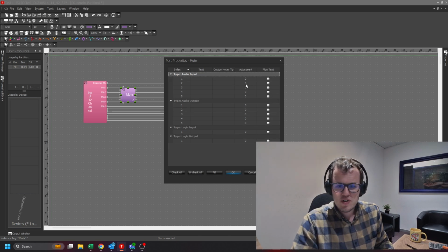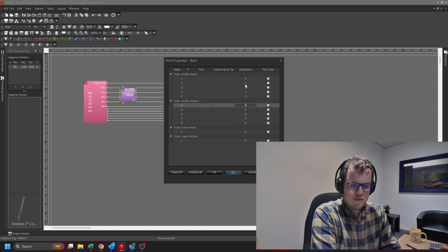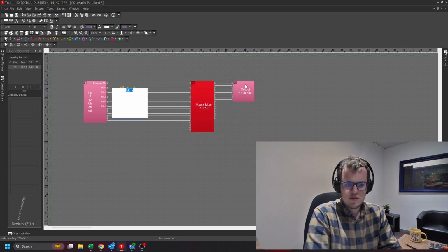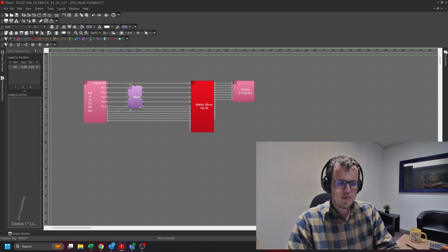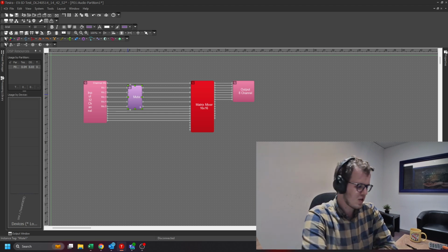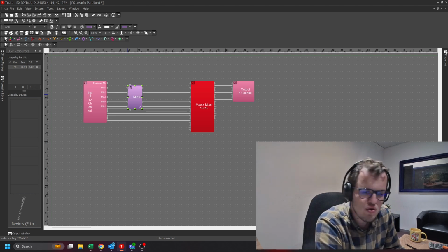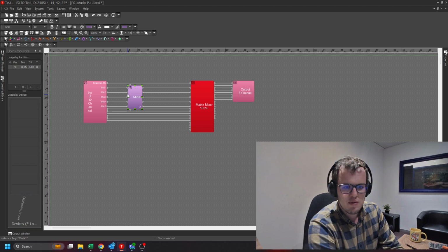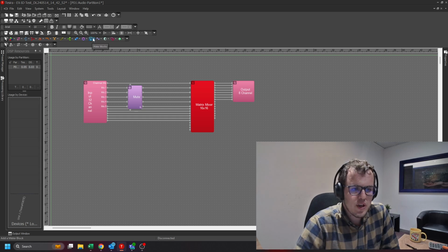So I'm going to just start off by spacing these out to match our design. If we line that up, there's a shortcut on Tesira that allows us to attach this block in line. If we press Control and I, you'll see that if I move the block, it moves the lines as well. Great, so then we can add a logic input.